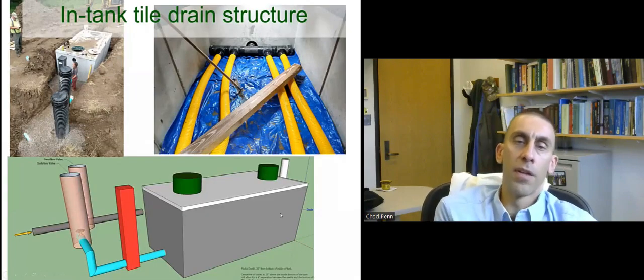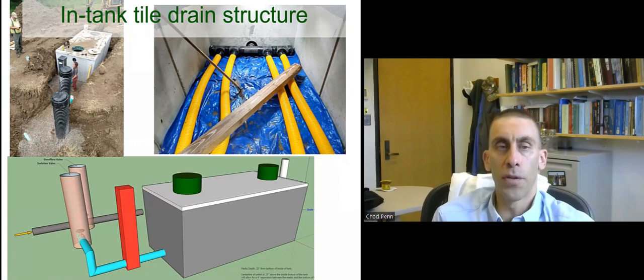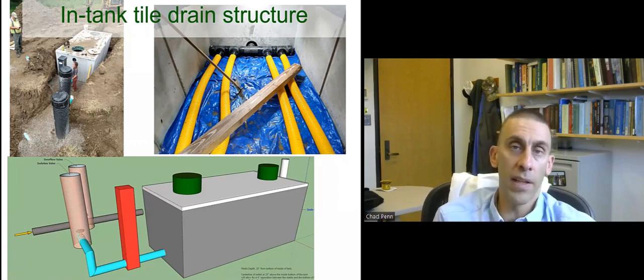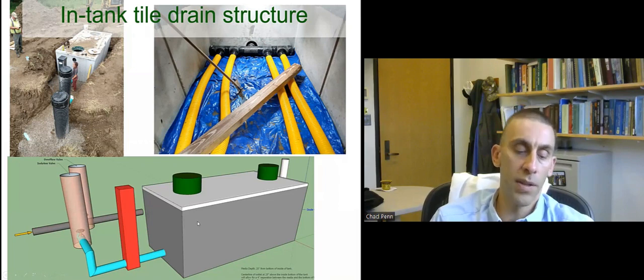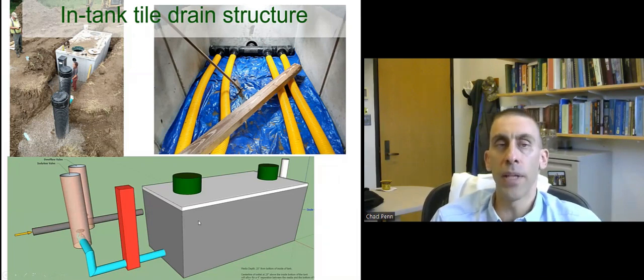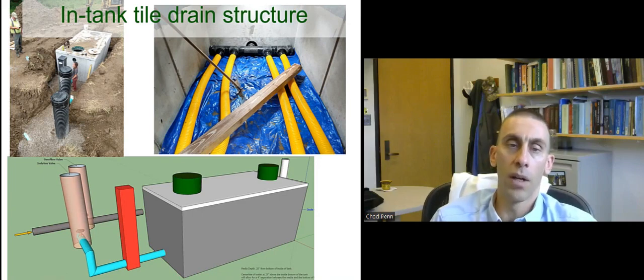So you can build the tile drainage filters as beds like that, or you can put them in tanks. We built several in tanks. The principle is exactly the same, but instead you contain your media inside of a tank. We do this when we're using fairly expensive media, manufactured media that we're either going to recharge or it has some value to us. We need to keep it clean or to be able to replace it and take it out. So same exact principle though.